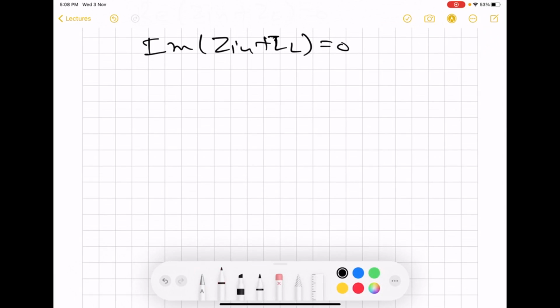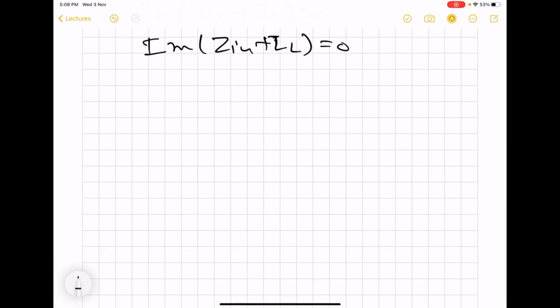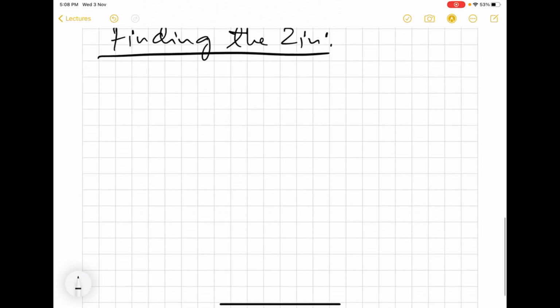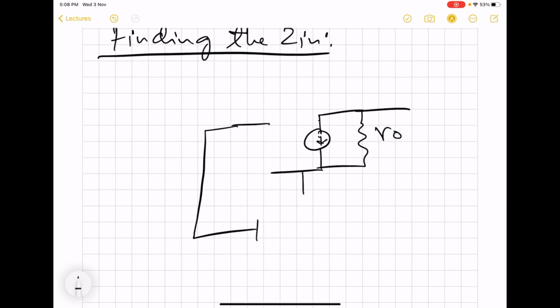So we are now going to set up the circuit for finding out Zin. For that, we will substitute the MOS by its small signal model and include C1, C2 into it. So we have our MOS here, and then we have these two capacitors, C1 and C2.